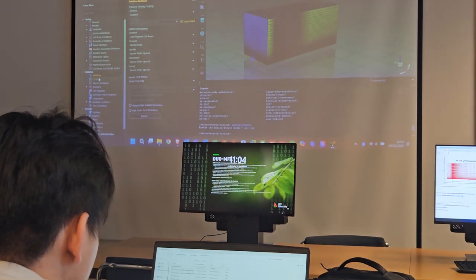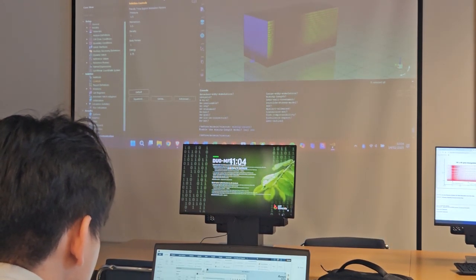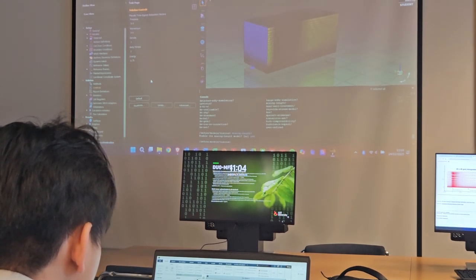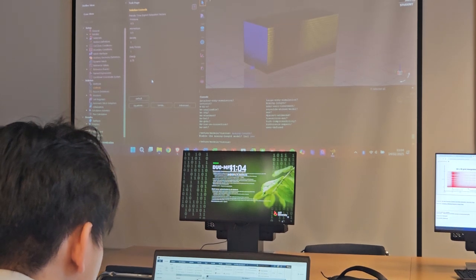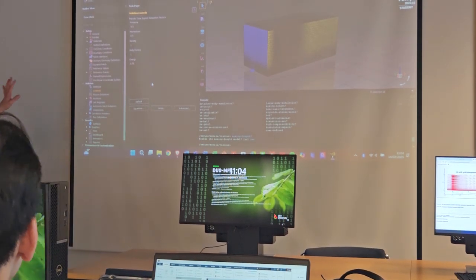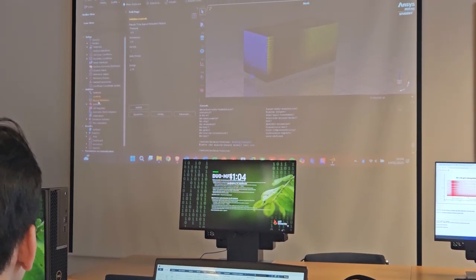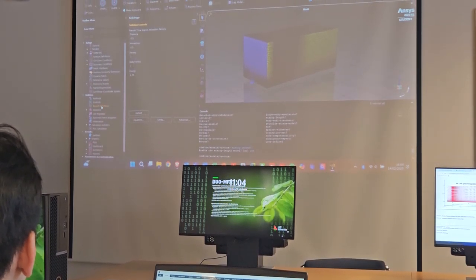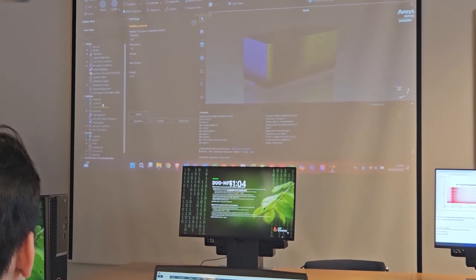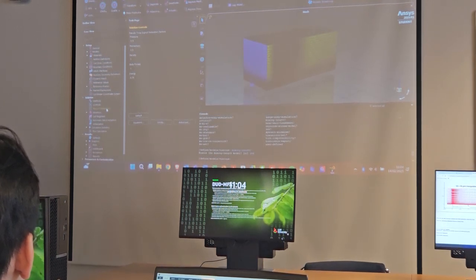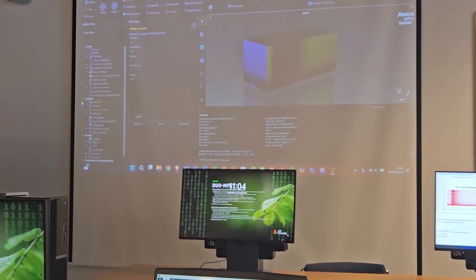So we didn't change anything here. You can go to controls. Here you can set some relaxation factors if you wish. Typically, you play with these factors if you see that you can't get a convergent solution. We can leave them as they are. Now we have set the methods and controls. What we can do next is to set how we get to convergence, so how we define a convergent solution.